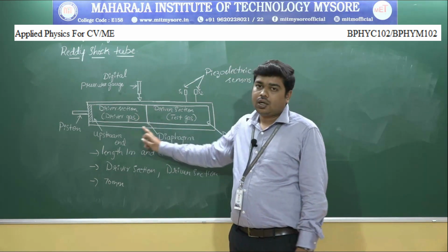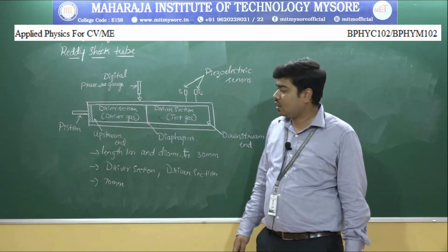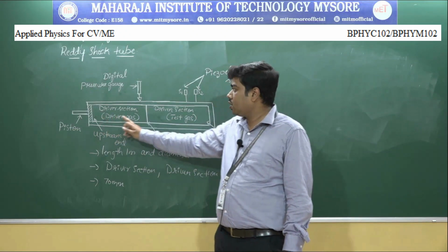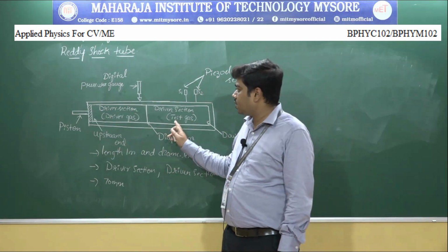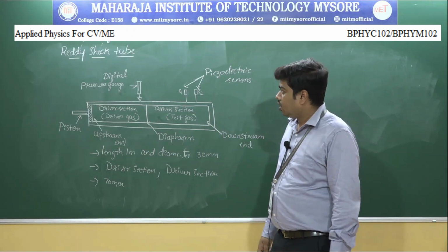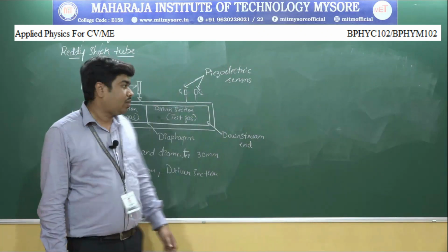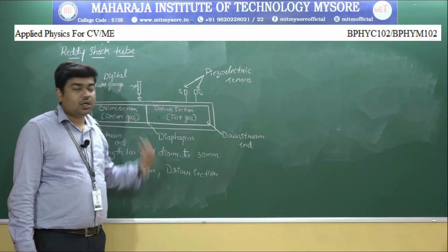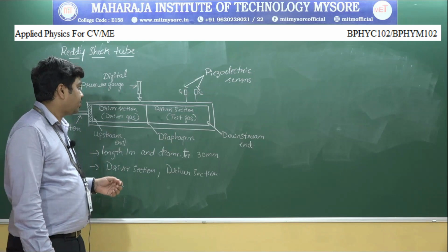But during the rupturing of the diaphragm there is another wave, called the expansion wave, which is created. This expansion wave also travels back from the piston towards the middle of the diaphragm, and the expansion wave and the secondary shock wave cancel each other. Because of the rupturing of the diaphragm, the primary shock waves are created, and because of the reflection back of the test gas, the secondary shock waves are created.